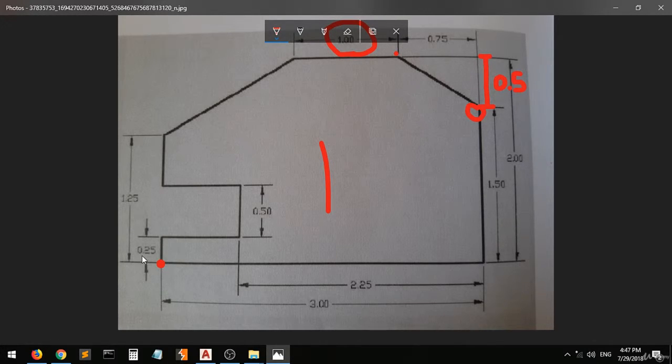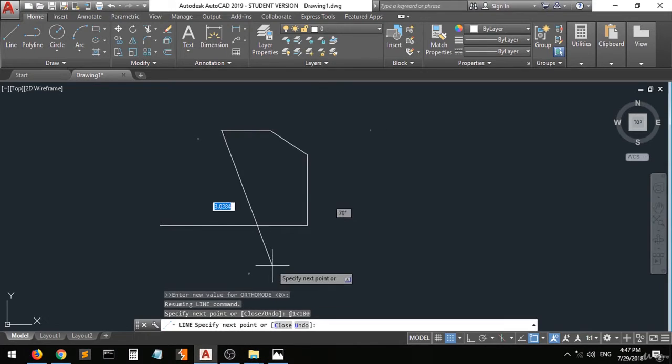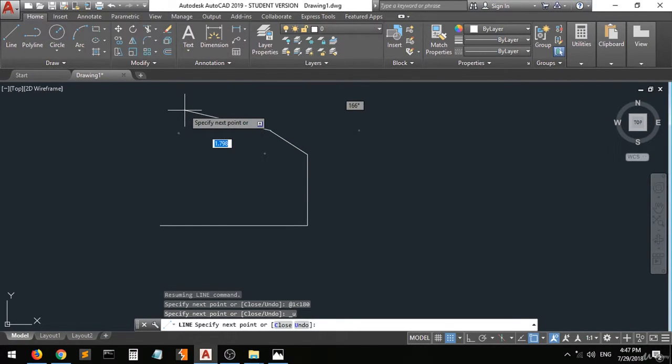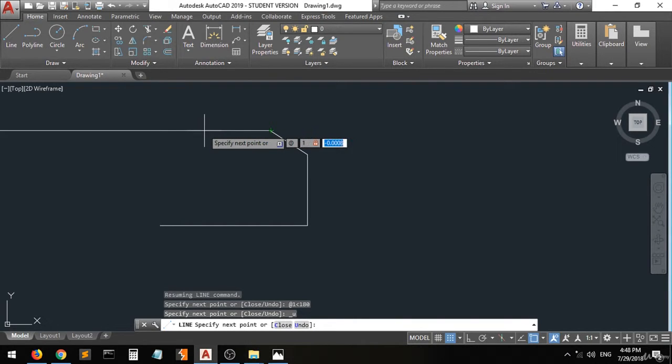Vertically with 0.25. But first of all, let's do this again in the coordinate entry, okay? We have put this in the polar entry. Let's do Ctrl Z for the undo. Now let's use the coordinate entry, okay? You have to type what the length, or the x coordinate, of this line is. It will be 1 slash, in the y-axis we're not moving, so we will type 0 and now enter.